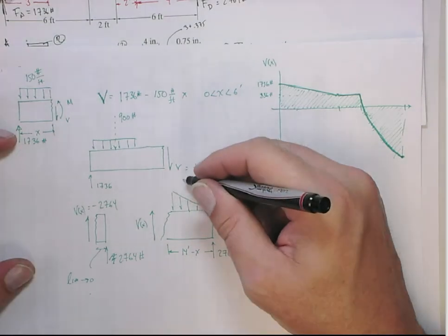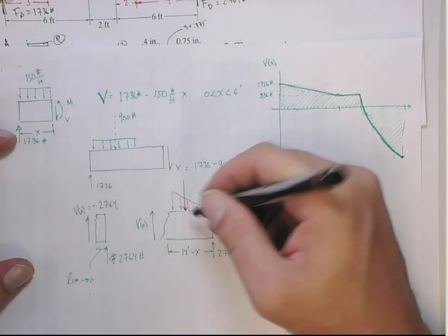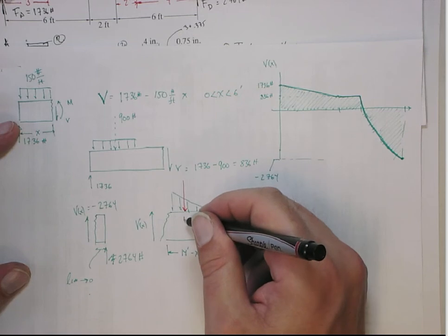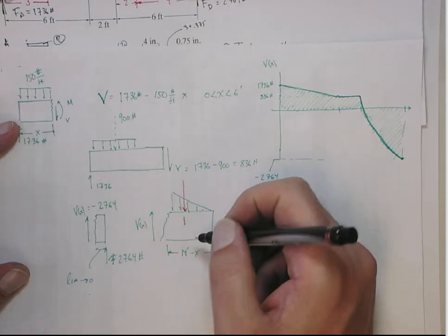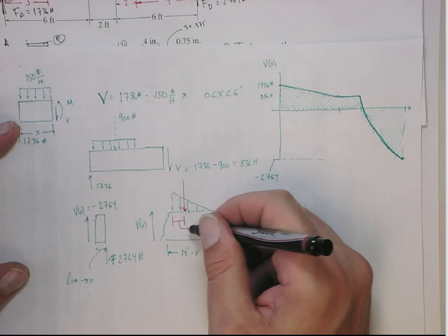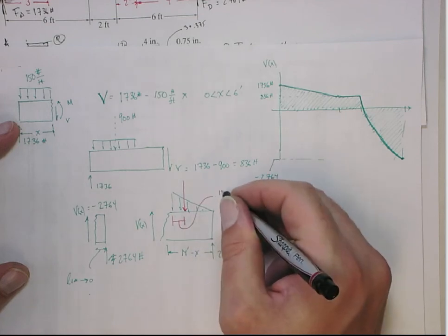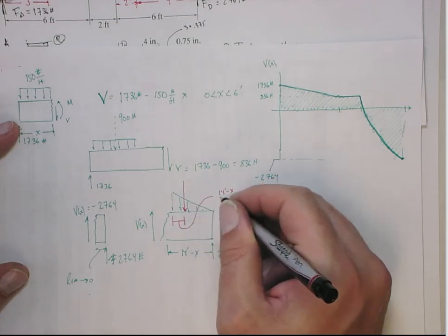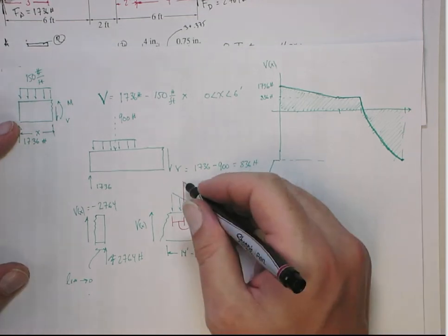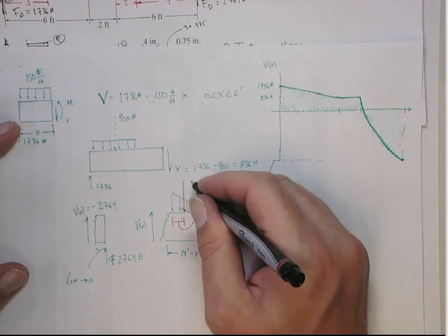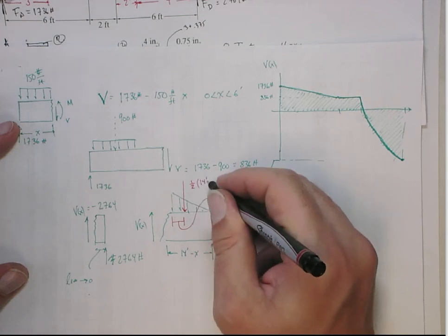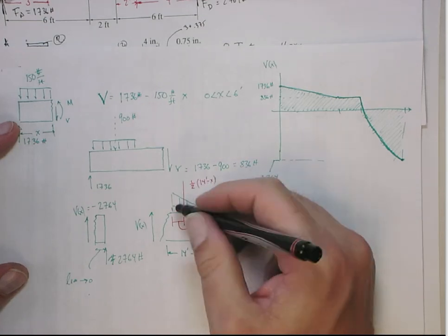All right? Now, if this is 14 feet minus x, I can get the effective force of this triangle. We can approximate it with a point force, whose distance here, well, actually, the distance doesn't really matter because I'm not going to give you some moments, but if you wanted to get them, this distance here is going to be 14 feet minus x over 3, right? And the total value here is going to be 1/2 the base, which is 14 feet minus x, times the height.